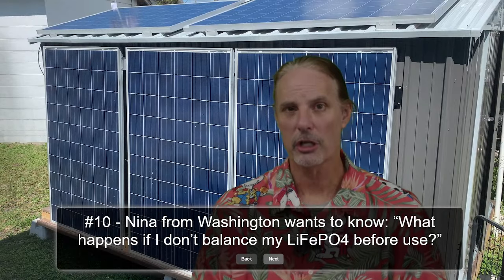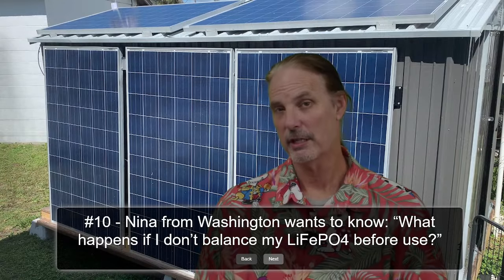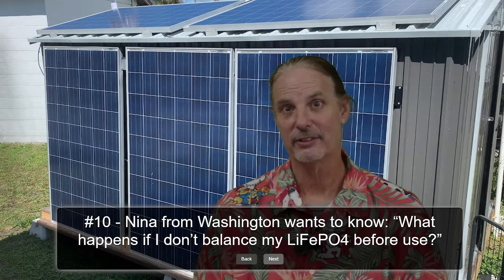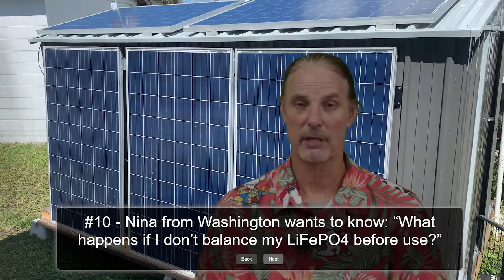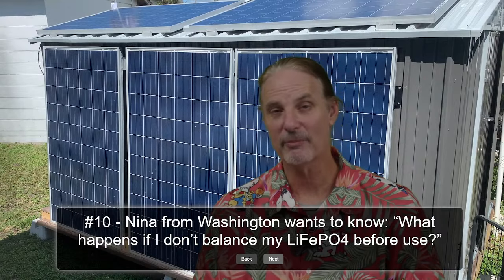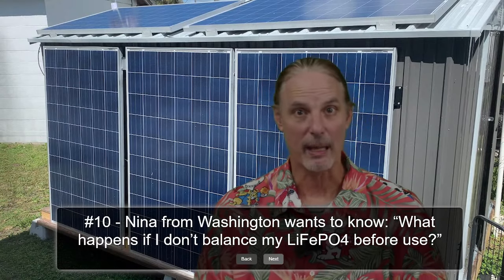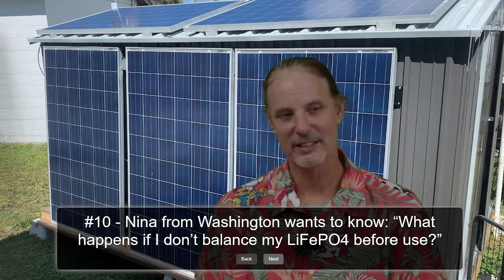If you're talking about a battery that you build yourself, like a DIY battery, then that would be a completely different scenario. It could be anywhere from it shuts off early until such time that the active balancer can get in and move things around, and that could take a while depending on how big your cells are and depending on how big your balancer is. Is it an active balancer that's moving 5 amps at a time? Is it a passive balancer that's burning off a tenth of an amp at a time? So depending on those cases, it's going to depend on what would happen.